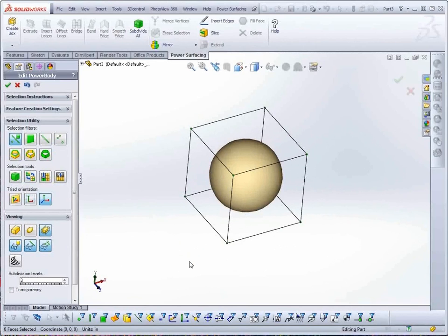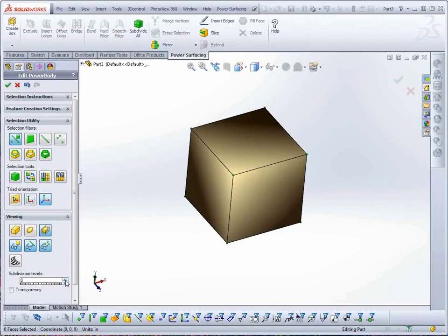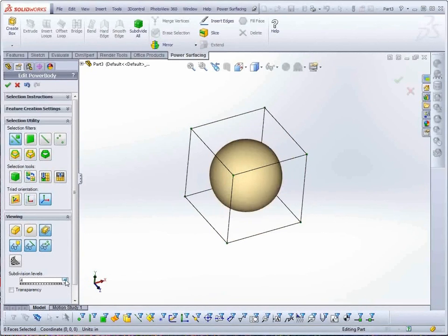It allows for easy manipulation of the faces, edges, and vertices from their control mesh locations while letting you see what the final Sub D mesh looks like. You can change the number of Sub D divisions displayed in the viewport from the Viewing section. Note that this will not affect the finished NURBS object.